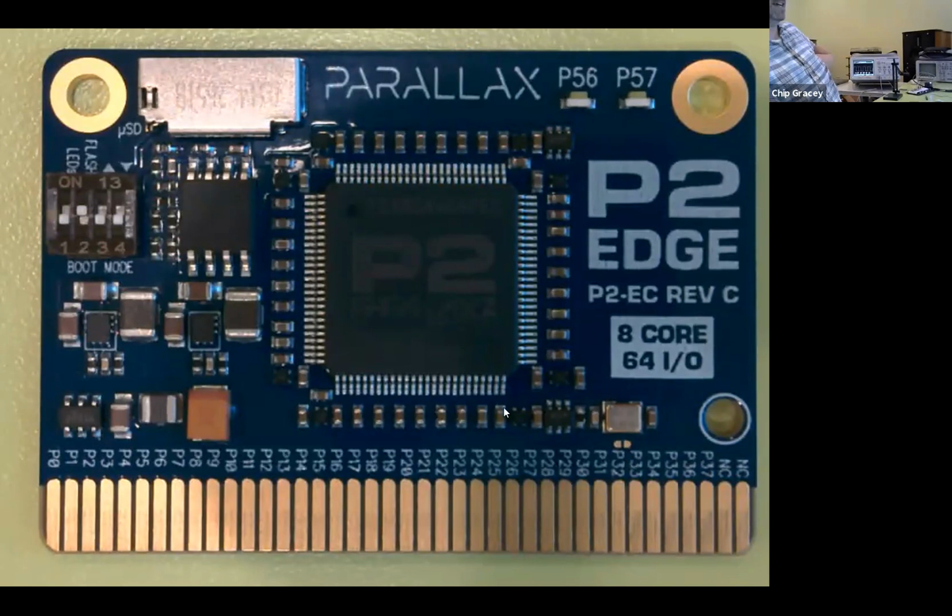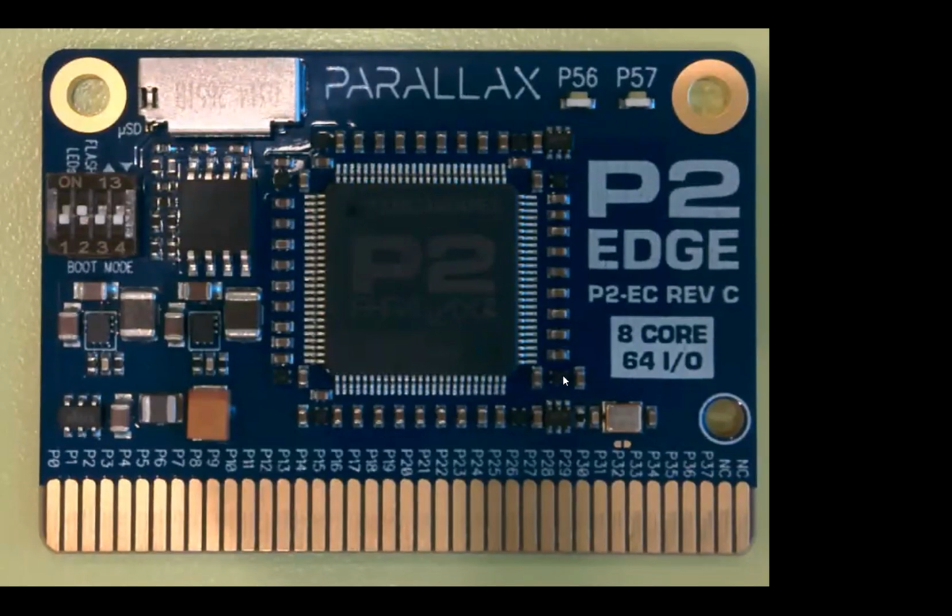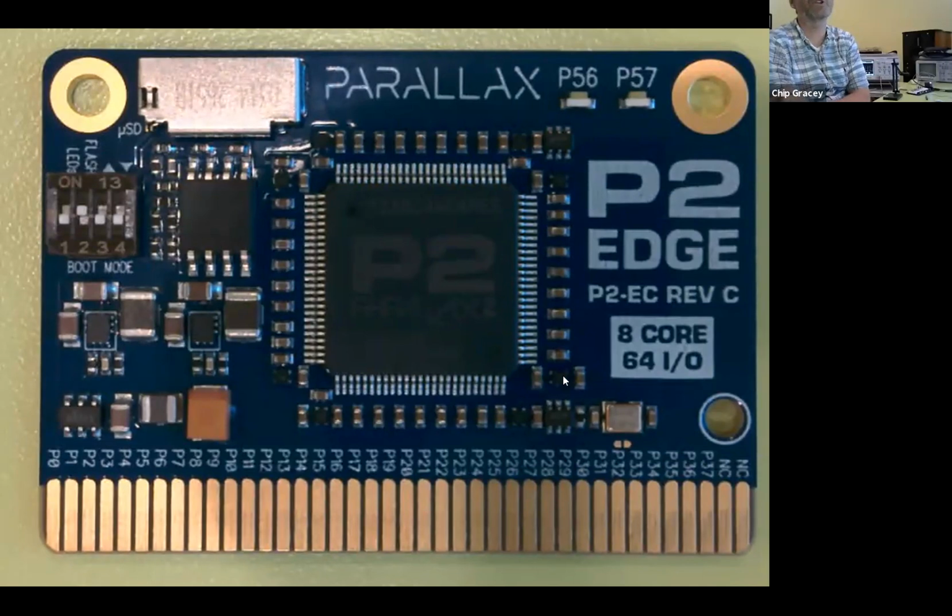Now, and I'll demonstrate that. Anyway, so we have a very precise and clean clock coming into XI. And this whole thing now, at 5 volts, this board takes about 3 milliamps quiescent current. And probably half that is this circuit down here. The other half is the quiescent currents from the switchers and the LDOs. But this has basically a rest current of 3 milliamps. And if you go up to like 10 volts on the input, it drops to 2 milliamps.